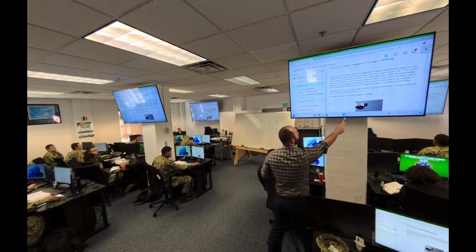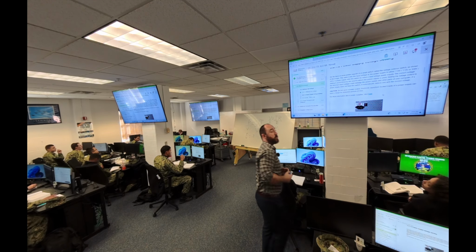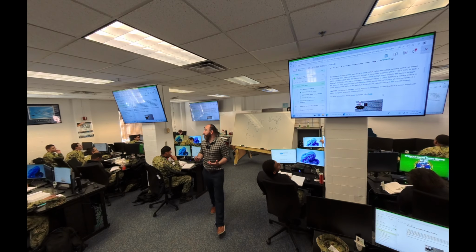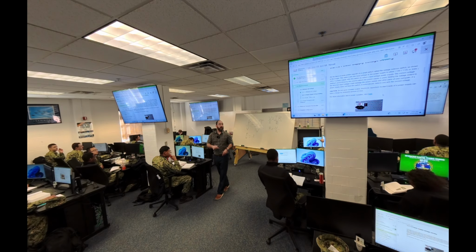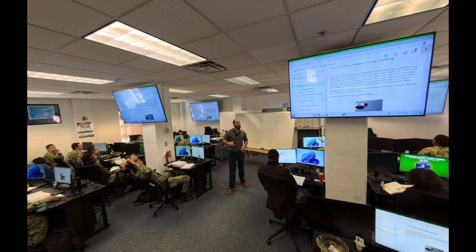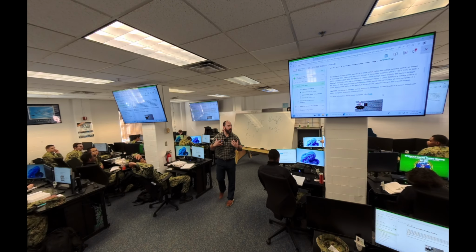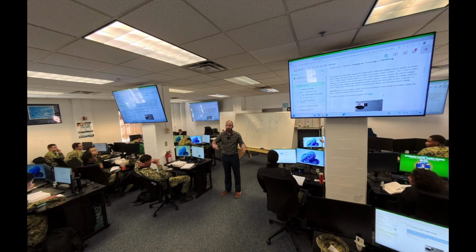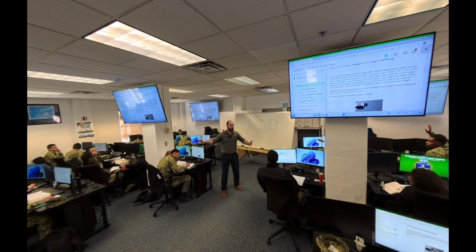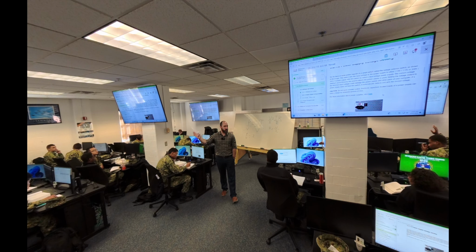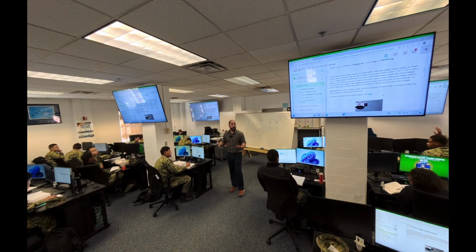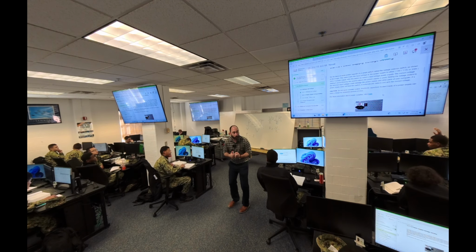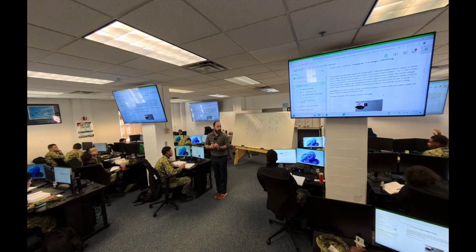So this switch right here allows us to choose between two voltages. What do we use in America? 115. But in other countries, they use 220, right? So if you're a company making power supplies, you don't want to make some for this country and some for that country. You just make one and ship it everywhere, and then they've got the option to choose. But voltage is how much work is required to move from here to here.